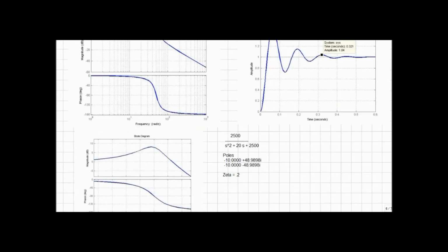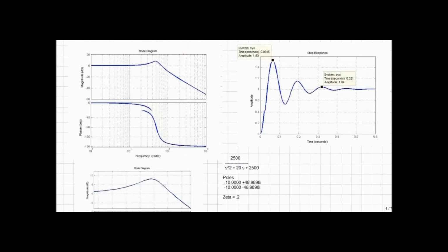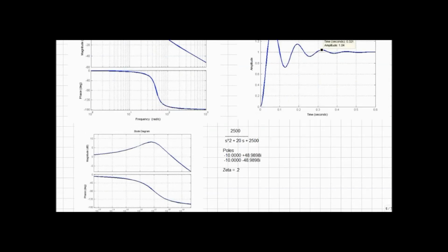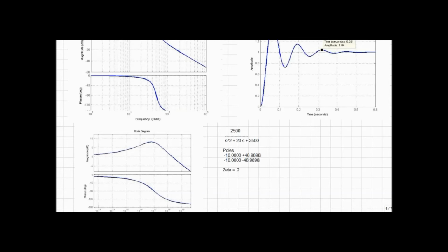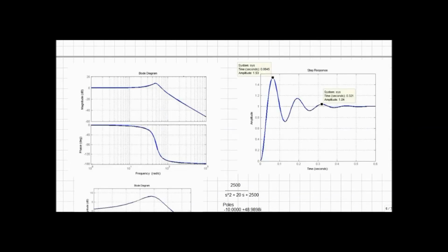So here we have another set of plots. In this case, I've set zeta equal to 0.2. We'll see how well we can recover that. Now I've got some good oscillations, so I can probably use the log decrement method and the other methods for finding zeta from the oscillations. If we start with a step response, I've got my damped natural frequency, omega d,